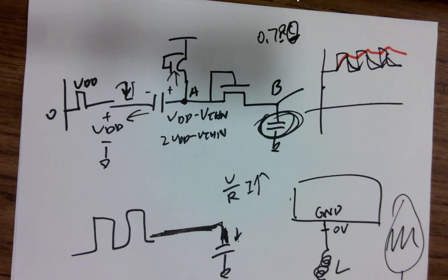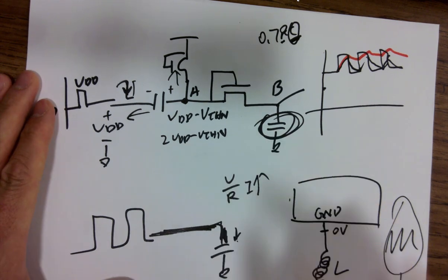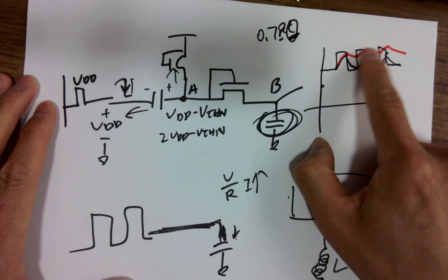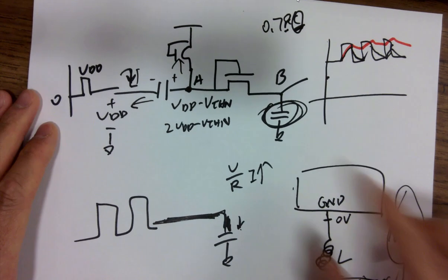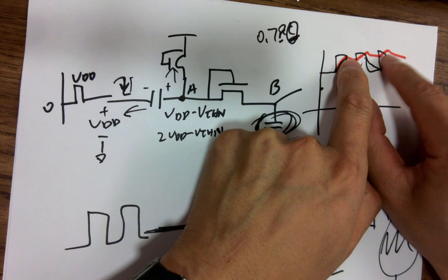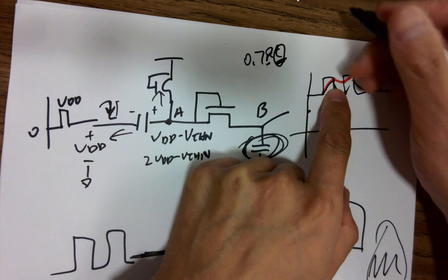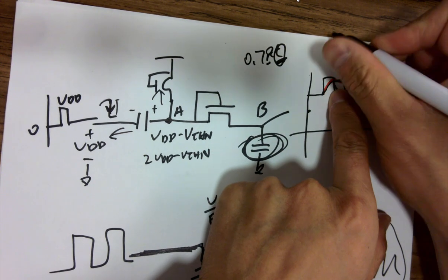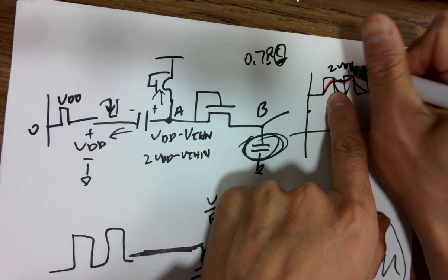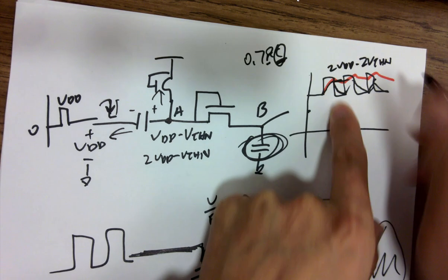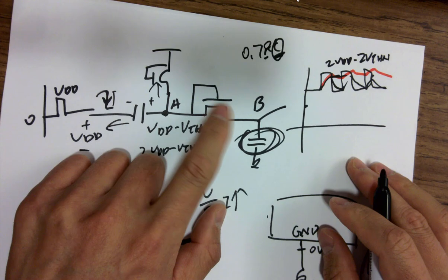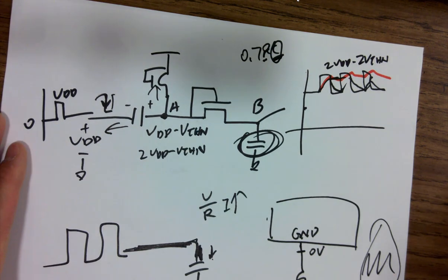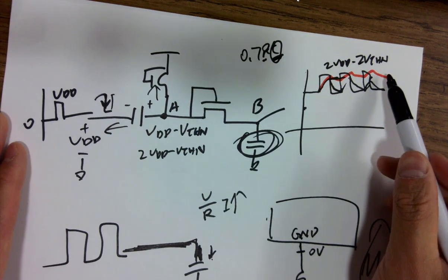Someone is dumping water in here. No ripples, right? So you just need a huge bucket in here to make this happen. That's the answer. And there might be a little decrease from this, so you are expecting the DC to be stabilized at around 2 VDD minus what? 2 VTHN, because there's a drop over here as well, but being smoothed out eventually.